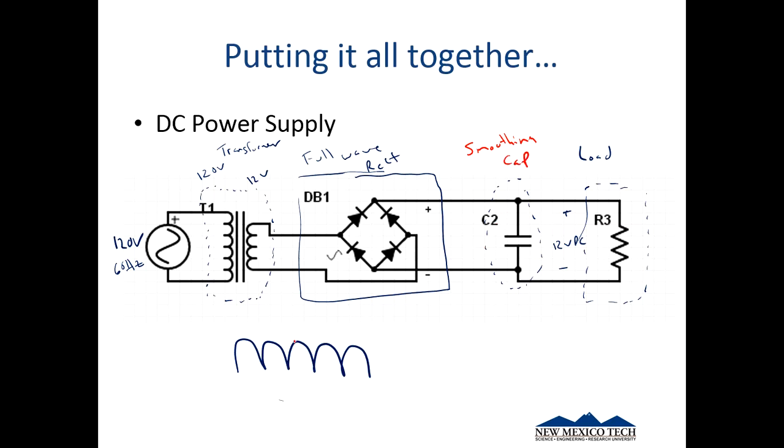And so basically at the peak here, we start charging the capacitor. We start charging it, somewhere down here. And when we get to the peak, this capacitor is now charged. Now our voltage starts to swing back down, and so we have this drop in our voltage. But now we can start discharging this capacitor. Then we get our upswing again. And we discharge this capacitor, and we discharge.